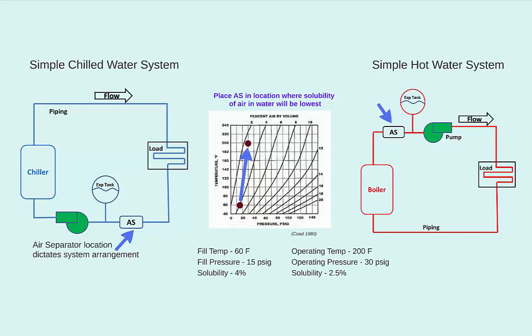So we talked about the best locations for the air separator, but why do we care to remove air at all? Well, if pockets of air enter the pump, the impeller will experience a sudden drop in force acting on it, since it is going from pushing water to pushing air. It is like when you're paddling a canoe. If the paddle comes out of the water sooner than you expect, the paddle speed will increase, and you might fall forward. In a pump, encountering such pockets of air will free spin the impellers for a moment before they catch up to more water.